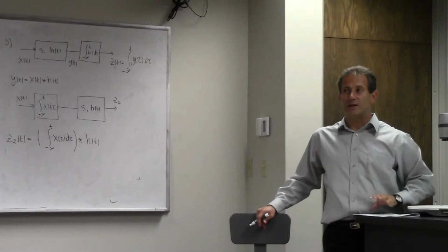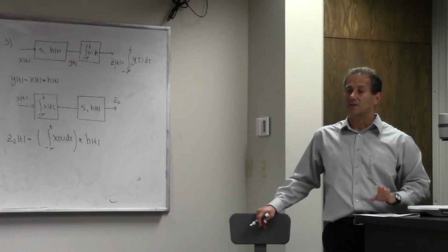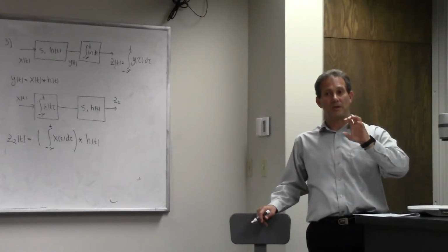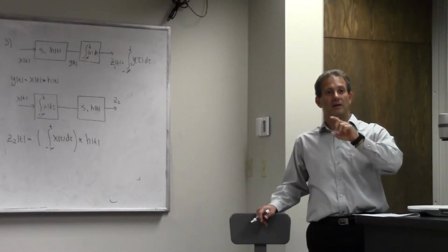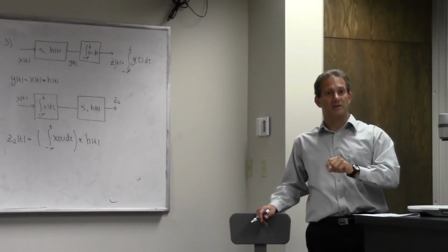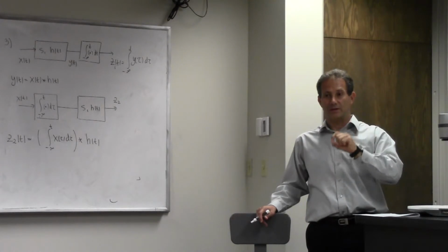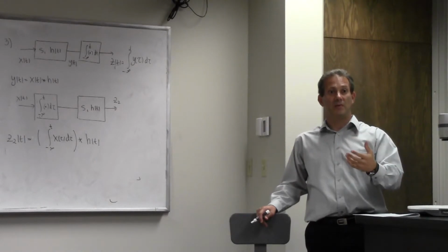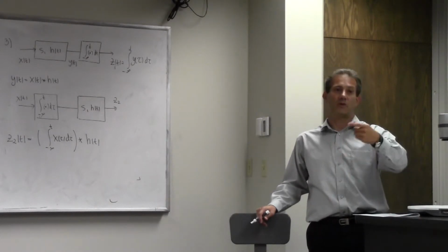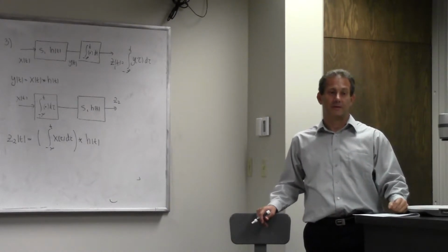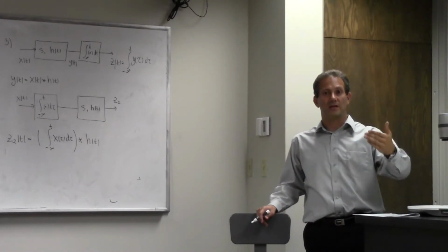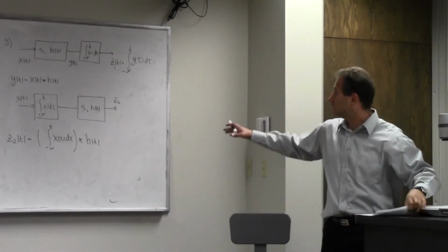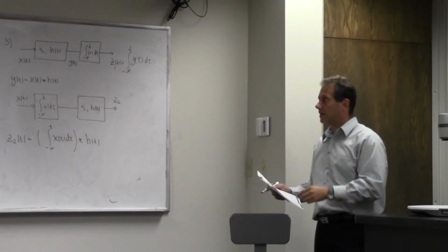Then we were able to find its impulse response relatively easily. And we showed that the impulse response of the original system you can obtain by differentiating the impulse response of the companion system, because the way they differ is that the original system had P of D, meaning that it actually differentiated the input before it was presented to the system. That was the whole derivation of how you get an impulse response in the time domain, right? So let's just go demonstrate this, and then I'll go back to that.